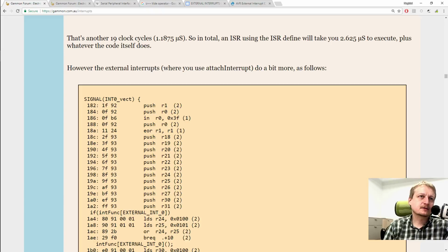Feko says, can't you just activate the motor back and forward there? No idea what that should help. Motor back and forward. Oh, you mean like not having the motor rotating in one direction, but rotating one way and then the other. Basically make it a servo. Use a DC motor instead of a servo. No, I don't think so. It's not good for a DC motor to change rotation direction so quickly. It's not built to do that. If you mean that.